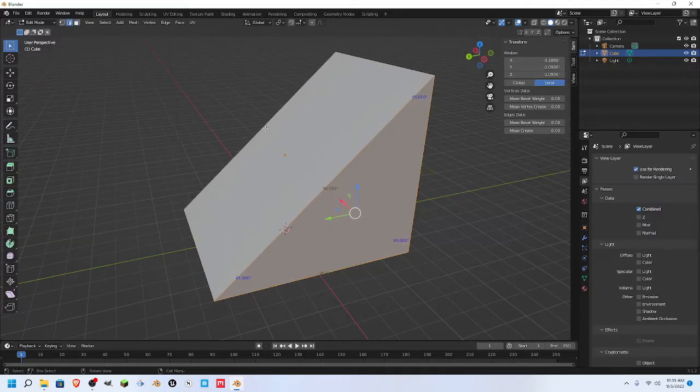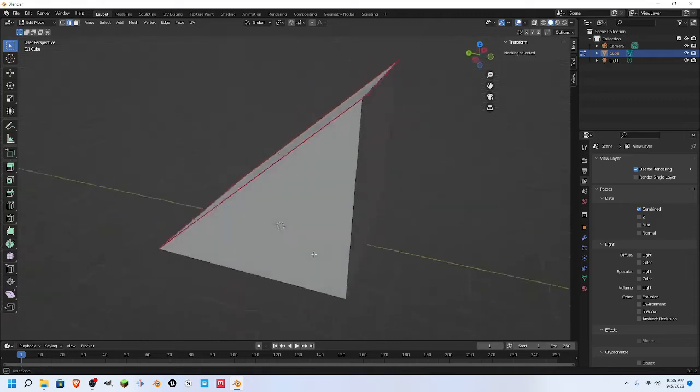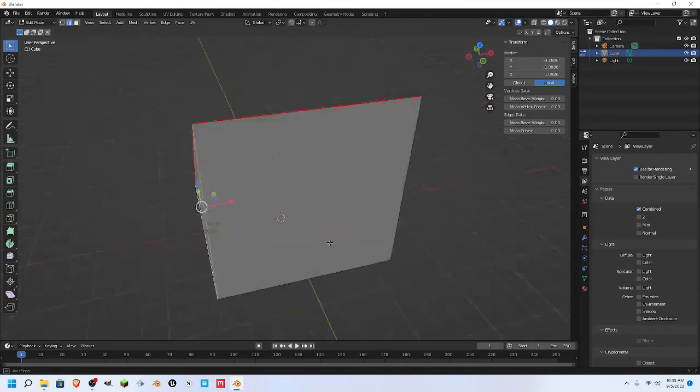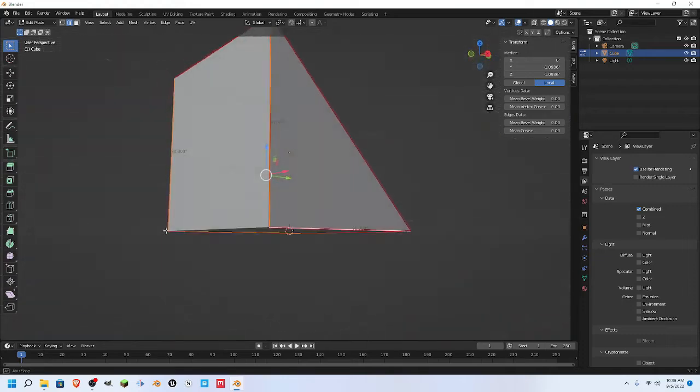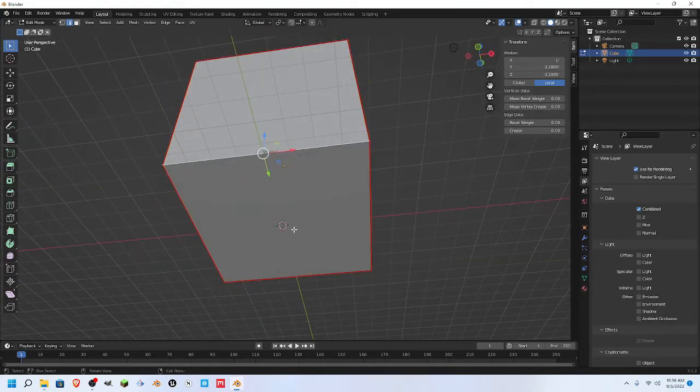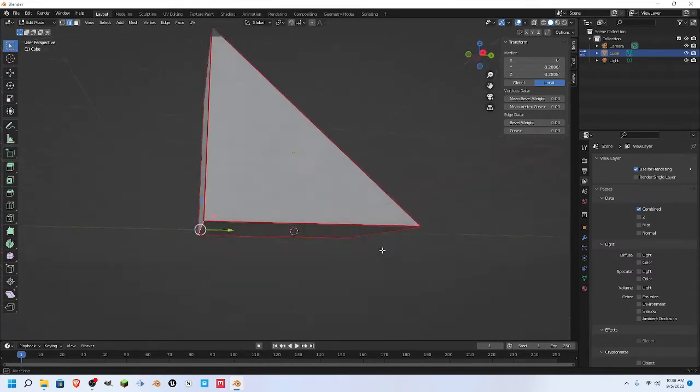Next, we're going to go back into edge mode. We're going to grab this top edge all the way around, because this is going to be one surface. Hit Control E and then M to mark it. And then these faces on the side are also going to be their own, so we're going to hit Shift R and duplicate that effort, and then this one on the bottom is going to be its own, so we're really going to be marking all of them today. Oh wait, that was the wrong button. Control E, M. So we've marked all of them.